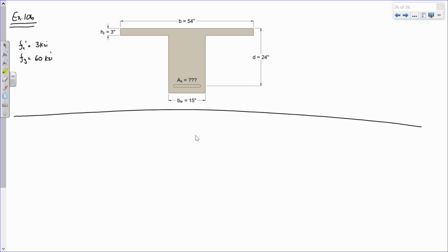But none of that matters because, the length for instance, the length of the beam would only be used to determine two things: your bending moment, which I gave you, and it would also be used to determine the effective flange width, right? Because remember, the effective flange width is the minimum of L/4, your bw plus 16 hf, or your girder spacing. But I gave you that because that's 54 inches. So it's actually not really relevant. Once you get your factored moment, the geometry of the beam actually sort of becomes invalid. So it's kind of an interesting observation.